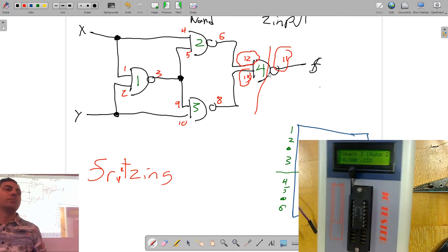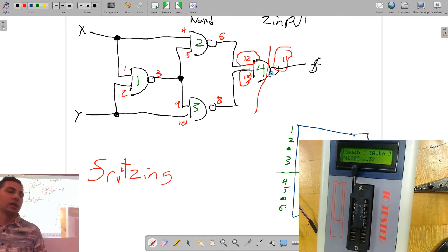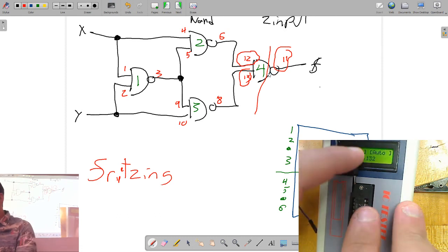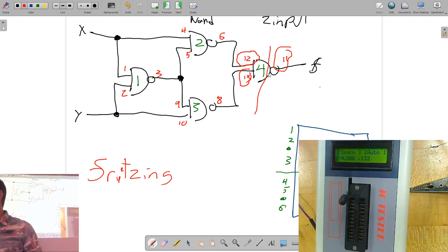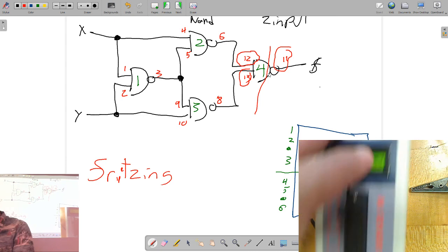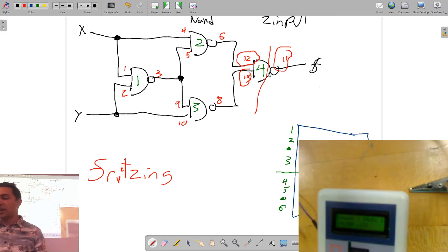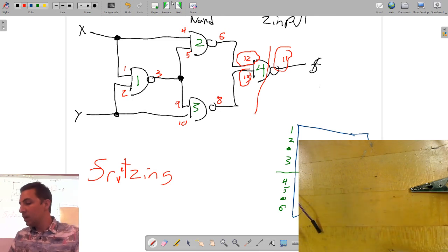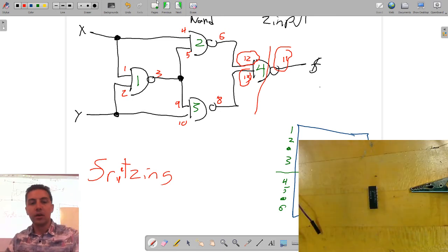132 is another chip it could be. It's the same pin out. It's a NAND gate. It's just a different thing. But the 7400 is what I want. I've got a couple of these testers lying around. I will bring them around to you and test your chip for you if you want. 99 times out of 100, it's not the chip. Okay? So, if it's not the chip, it's got to be one of the inputs.